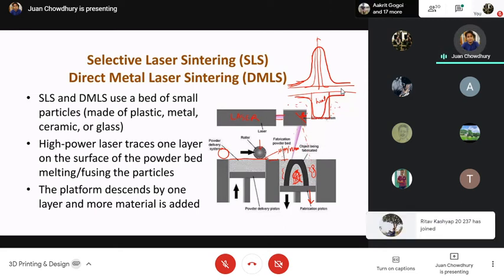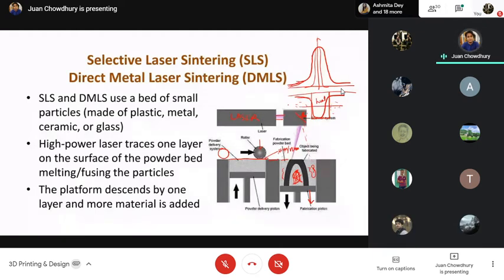Again, the criteria is that what should be the optimum layer thickness based upon the penetration depth of the layer, isn't it? If you make the layer thickness really small and keep the penetration depth really high, what it is going to do is also distort the lower layers, which you will end up not getting the part that you wanted with the right amount of surface texture. Okay,